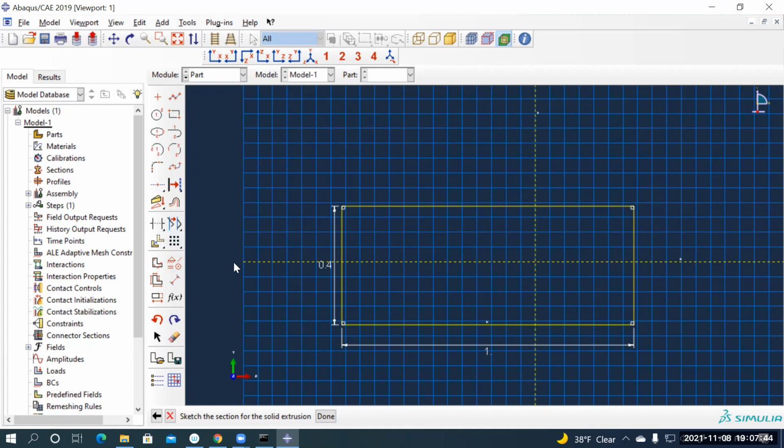So we're going to make this rectangle center to be exactly the origin. And the way to do that is through relations. Look for the relations, add constraint. You would see it as a triangle, equal to, with those signs. So select the constraint option.